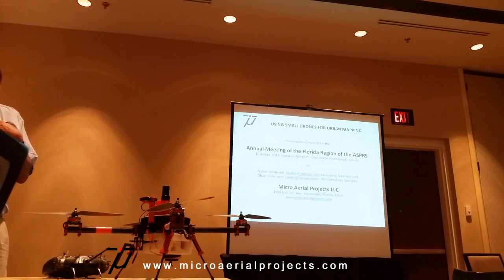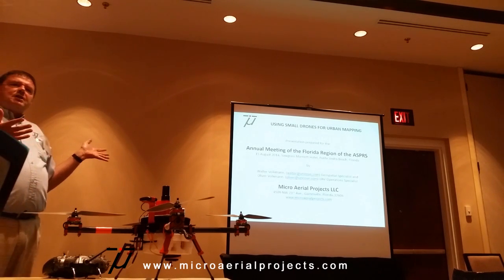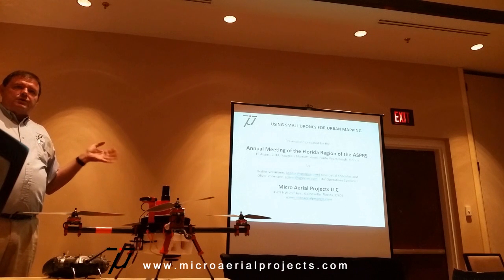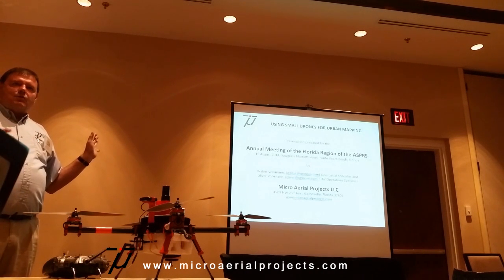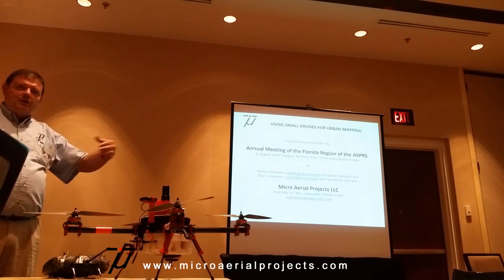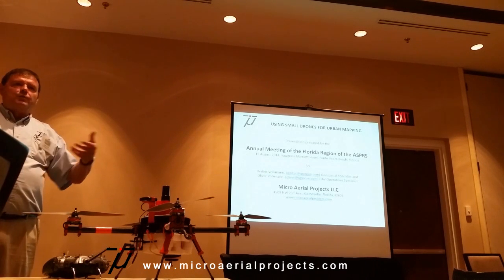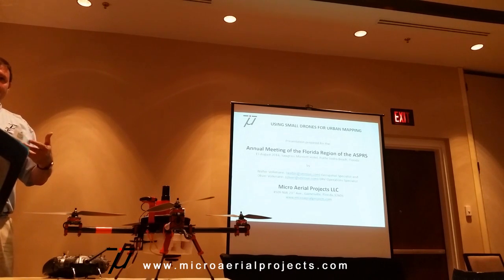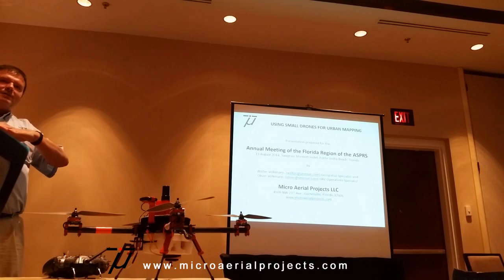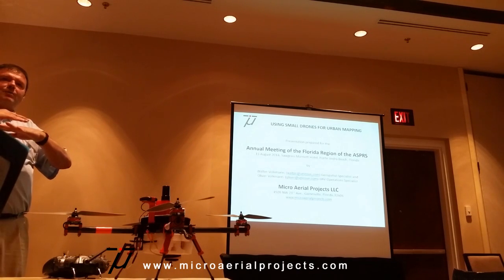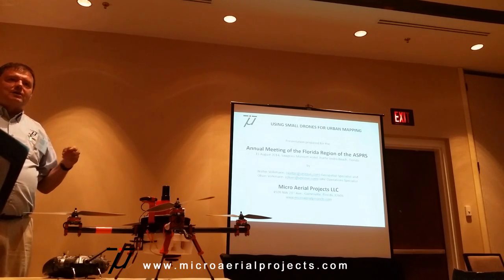But being a land surveyor, I'm phobic about accuracy all the time. So, you know, we had about six to 7 points over 30 hectares. And we actually organized the job in such a way that we have 7 blocks, and we performed a separate adjustment for each block. And where the 2 blocks meet, we could then compare how good our mapping was. And that was very enlightening to us.